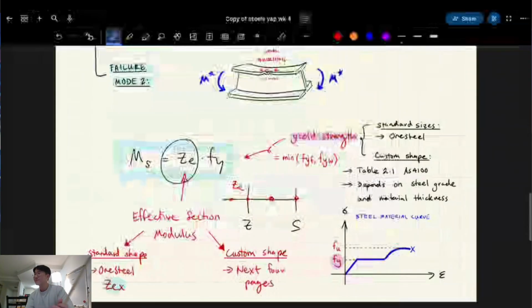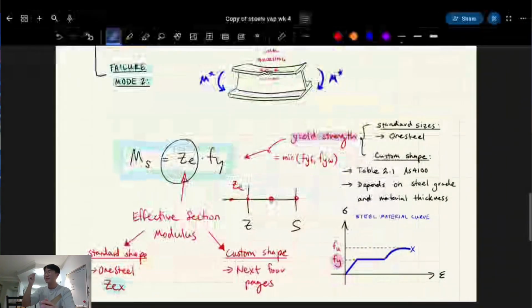So did we actually need to find Z and S earlier? Yeah. We have to. I haven't even shown you how to calculate ZE, but it's in between those numbers, or slightly lower if it's slender, right? But the other thing is we don't have to calculate S if we have a slender section, because it's only dependent on the variable Z. Because if it's all the way to the left, we don't care what S is. So the solution's monotonic. Do you think Z or S is bigger?